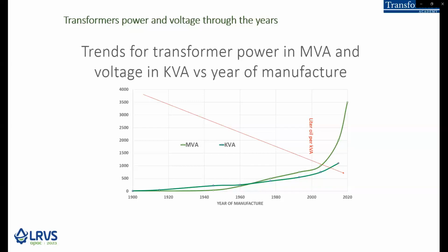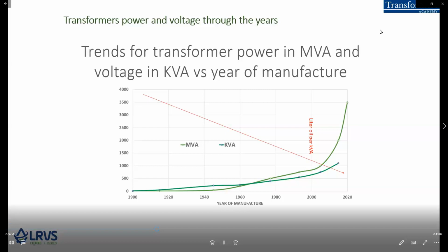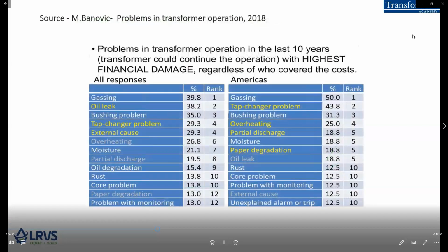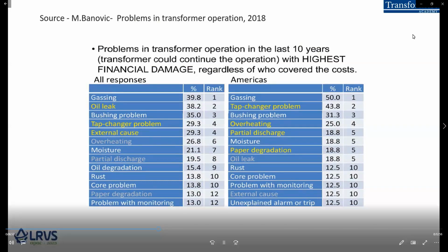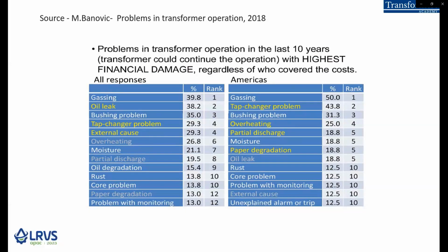The transformer produces much more heat. The heat loosens the insulating property of the insulating matrix, reducing the conductivity and the insulating properties of the oil and accelerating the aging of all the materials inside the power transformer. The elevated temperature also promotes the potential occurrence.